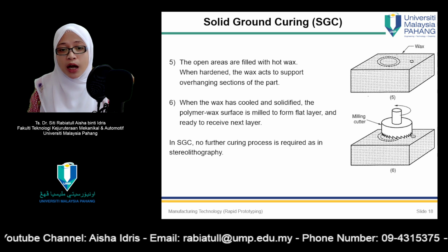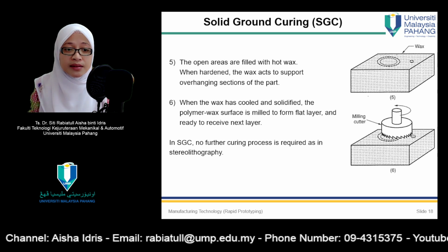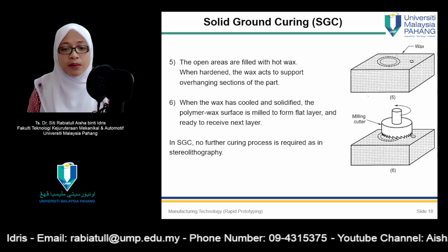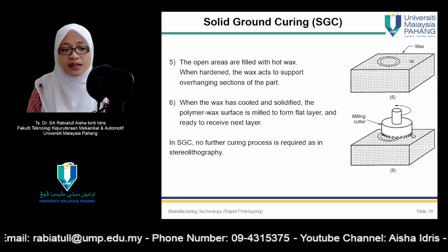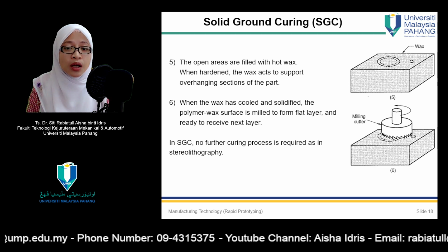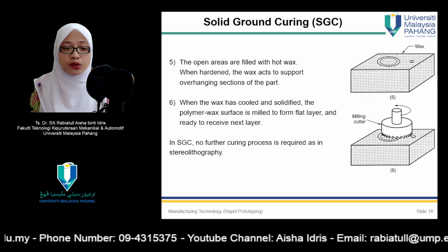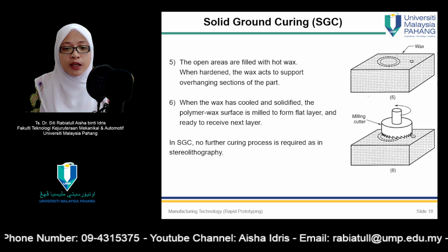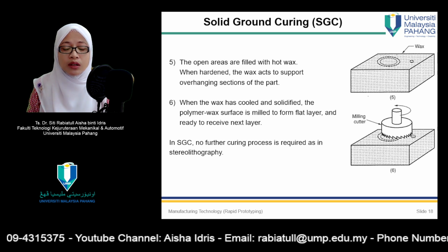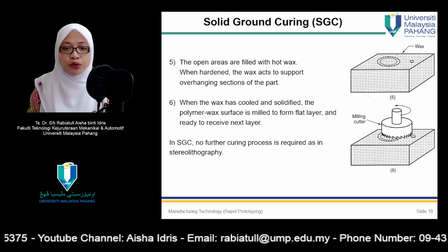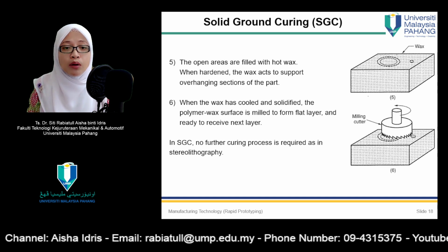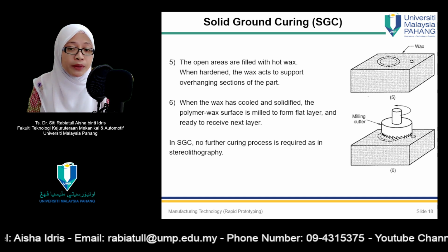Although we have described SDC as a sequential process, certain steps are accomplished in parallel. Specifically, the mask preparation step 1 for the next layer is performed simultaneously with the layer fabrication steps 2 through 6, using two glass plates during alternating layers. The sequence for each layer will take about 90 seconds. Throughput time to produce a part by SDC is claimed to be about 8 times faster than competing RP systems.